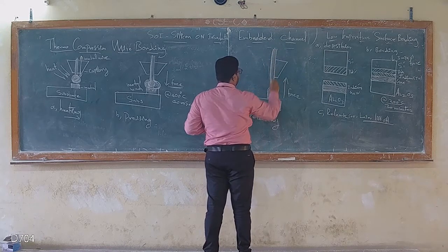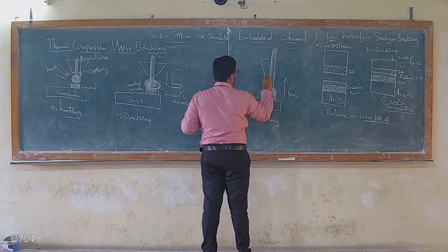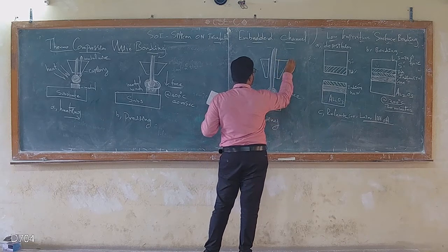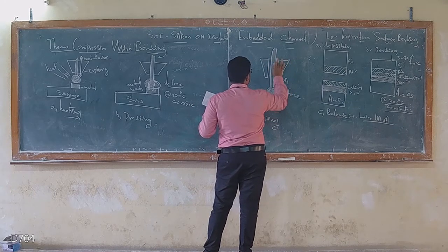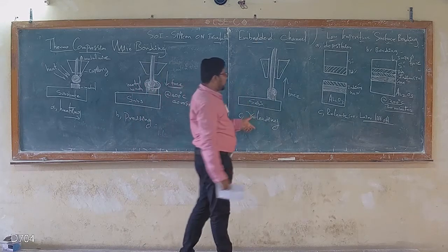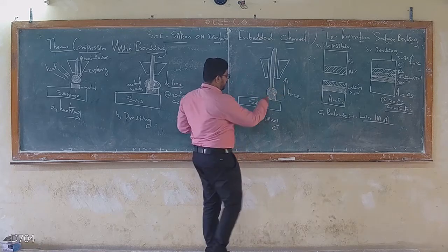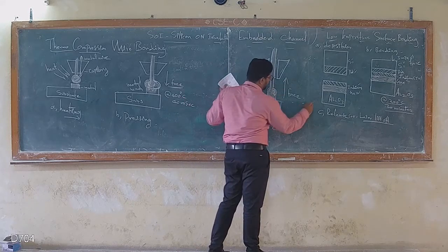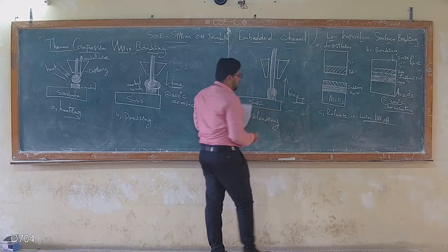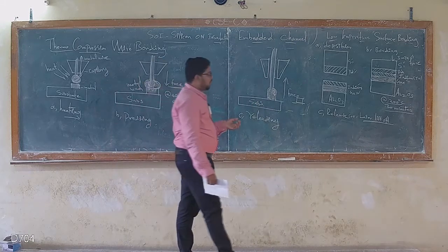So this is the wire. I'm going to release the capillary, so the capillary moves upward. I released my wire and moved upward, and sometimes it may extend to the next one. So we made one connection, which may extend to the next metal on the same substrate. Because it's wire bonding, we may have an infinite number of wire bonds if necessary.